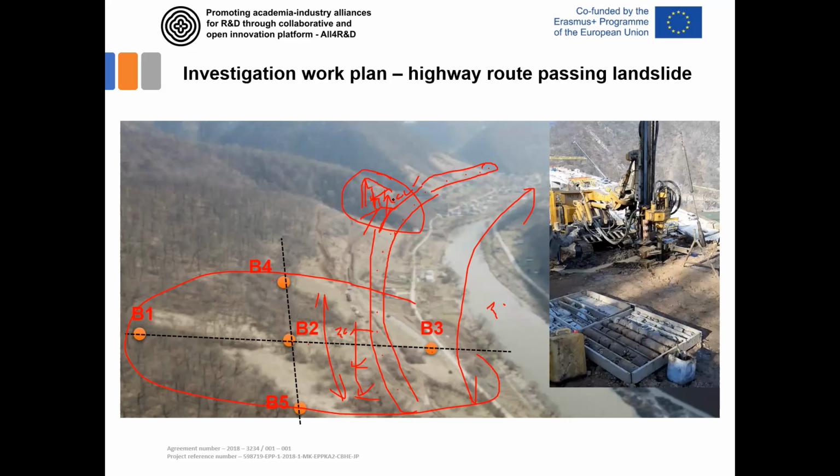So what I think is that this minimum of 200 meters for line objects like highways is definitely not enough for the special condition, very special condition like here. The highway location where 200 meters was appropriate could be the north part of Bosnia, where you have the river Sava and flat area all around it, where the conditions at 10 kilometers are practically all equal. It's some clay material and some gravel, sand, clay, sand, like some cake with some layers of alluvial soil, sand, gravel, clay, sand, gravel, clay.